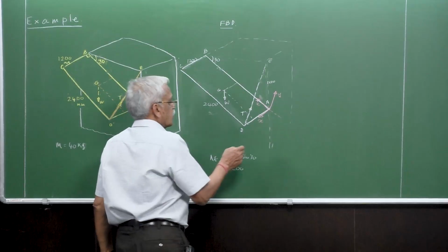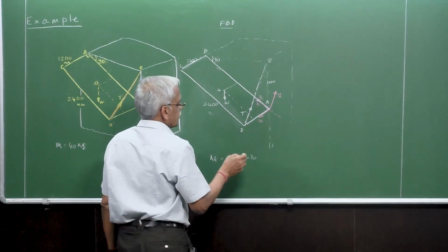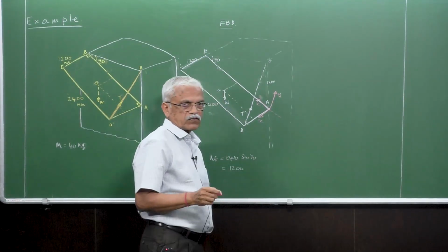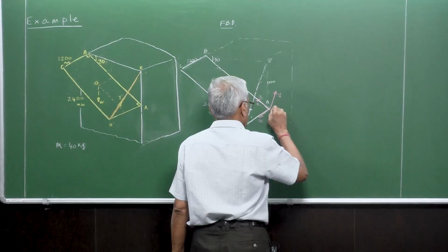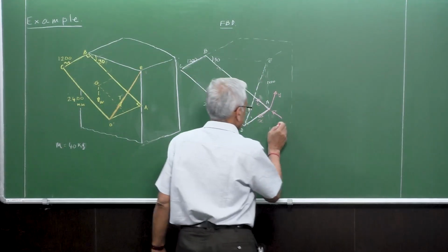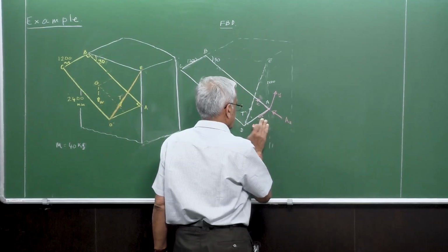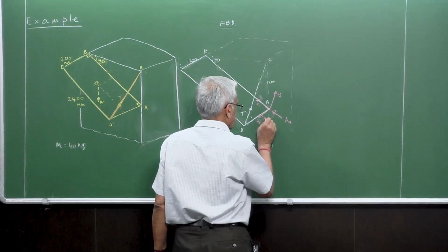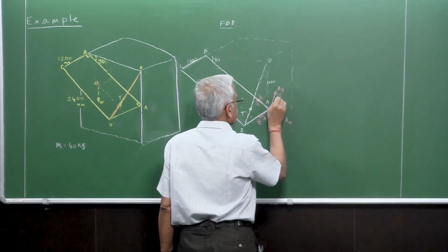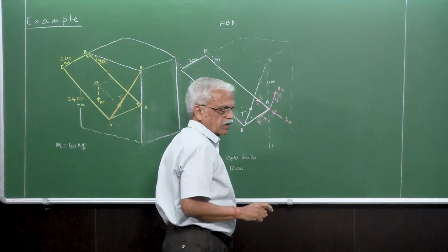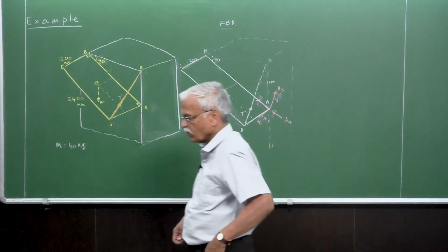And so why we have chosen this axis is that, similarly here of course the same axis, and here we show the three forces because this is a point support. So we show these three forces here at point A. So this we call as AZ. So AZ is the force, and this is AX, and here this is AY.